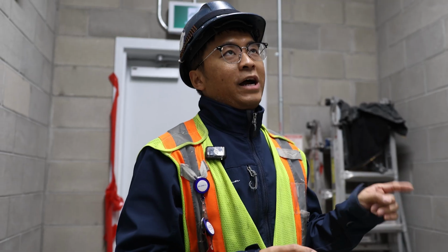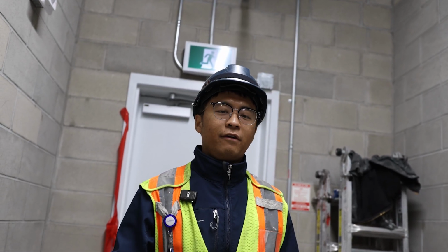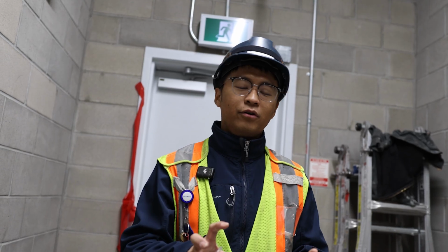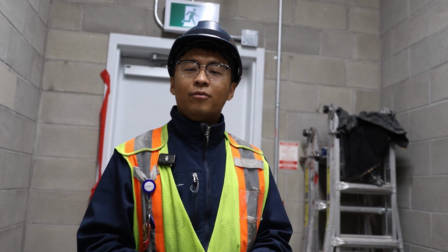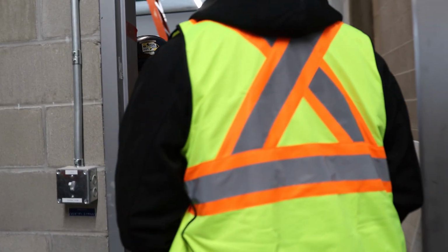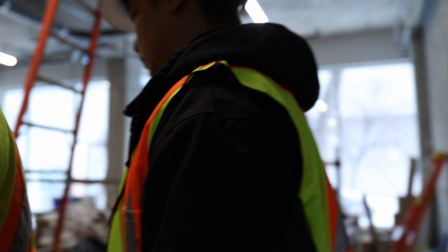So HRV2 and HRV1, they are the same unit, just different control. HRV2 and HRV3 are controlled by the timer, standalone units, but HRV1 is controlled by DDC because HRV1 shall be running the whole time to reject the heat in the data room. And then I will show you the location for fan coil 7 and the HRV3. They are the same unit, I'll just show you the location.